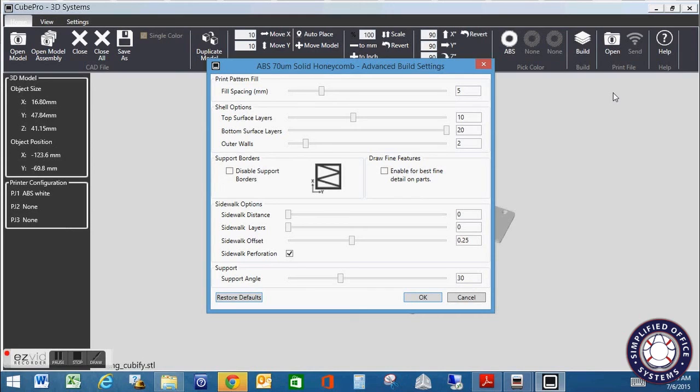When you put down more material, it's putting down exactly that, more material on that bottom layer. And what happens as it cools, that bottom layer has a tendency to start popping off the plate. So what you will see is as you turn that down, you actually don't lose detail. You're just putting a little bit thinner layers on that bottom, so you have less of a tendency of it to curl or to pop up off of the plate.